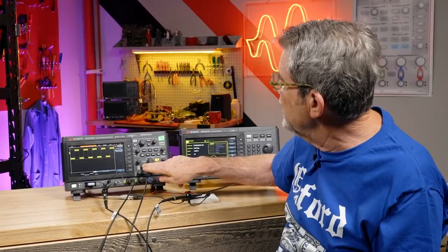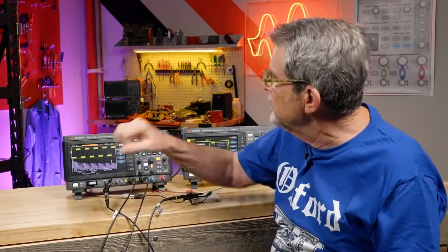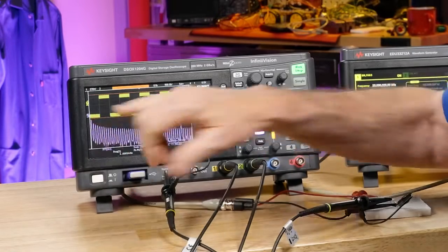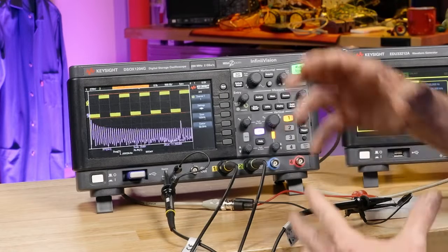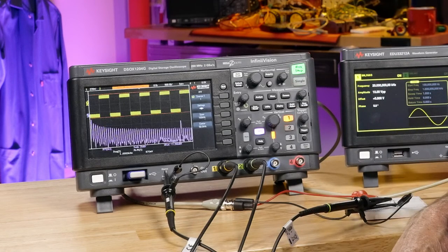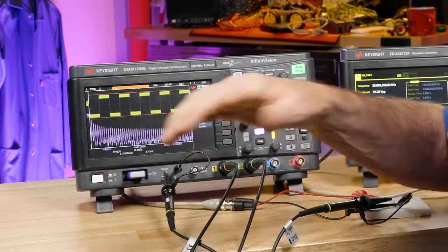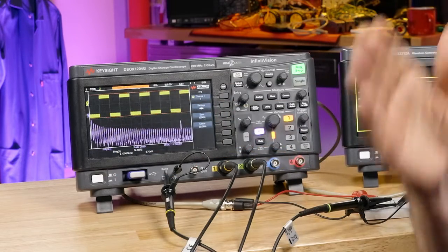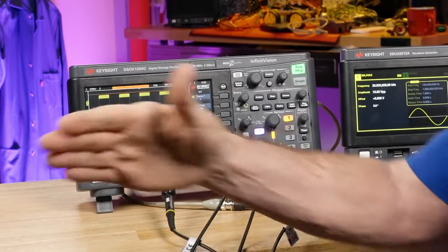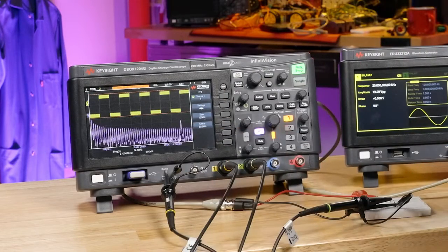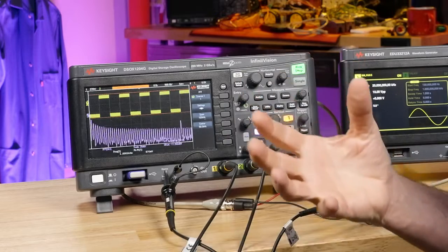So I'm going to turn on FFT, and I've already got the span and the center set up to demonstrate this. This is the fundamental way at the left. If I put cursors up, I could measure it. I would see it's at 1 kilohertz, and then all the other peaks are 3 kilohertz, 5 kilohertz, 7 kilohertz, all of the odd harmonics of the fundamental. You add all those up, and it has sine waves, and it creates the 1 kilohertz square wave.